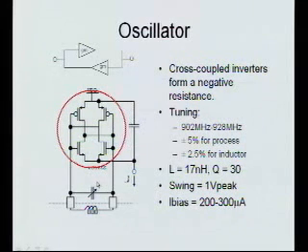Now, if you put a high Q LC tank across this, the place where this is highest resistance, where it least strongly resists the negative resistor, is at its resonant frequency. So it'll be unstable at the resonant frequency, and it'll oscillate. And so now you've got an oscillation that's set by the LC coefficients of your tank here. This is basically the most common type of RF oscillator out there.